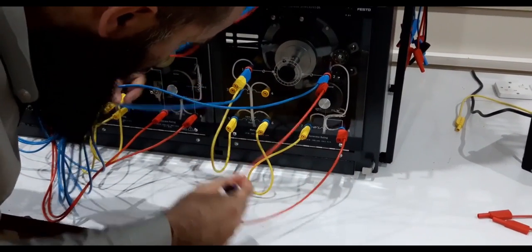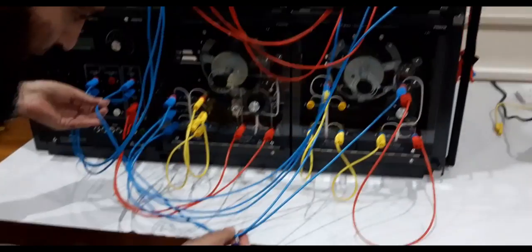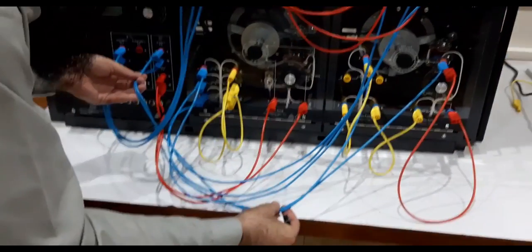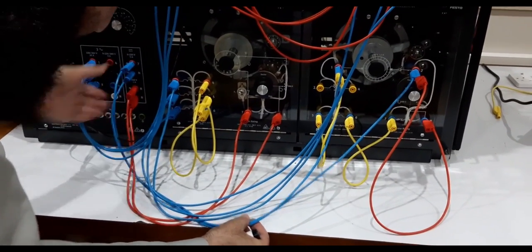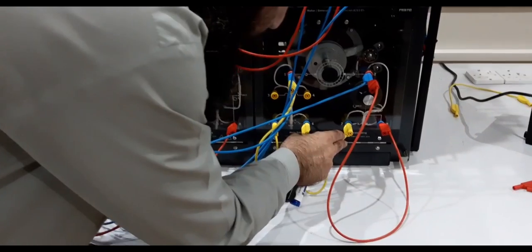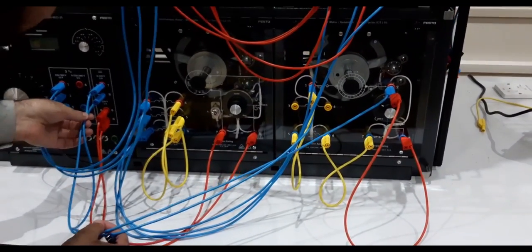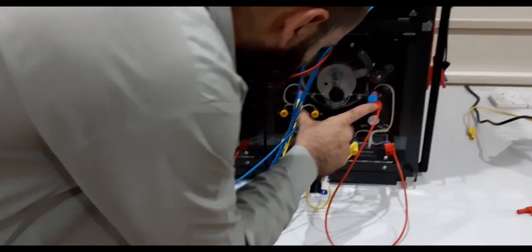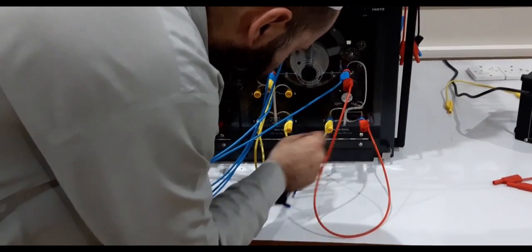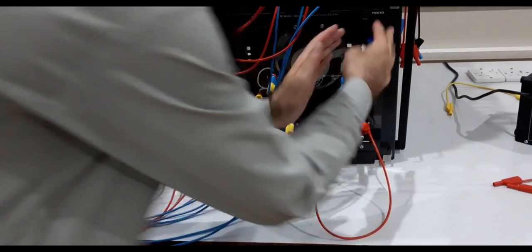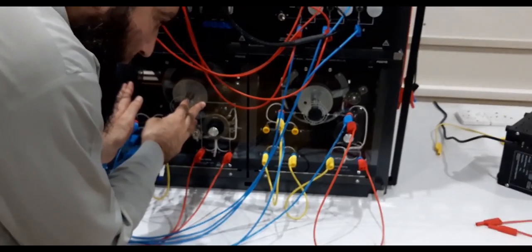One can see here, these are the two connections coming from the variable supply, because I mentioned there that we will change the speed of the DC motor by means of either varying the voltage or by means of varying the field. So the armature is connected to the variable voltage source, and this is in parallel to that of the field winding. But we also put a rheostat in the field winding in order to vary the field current. So this DC motor will act as a prime mover for the generator.